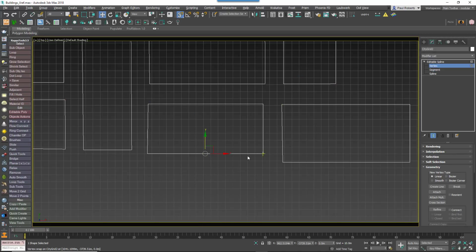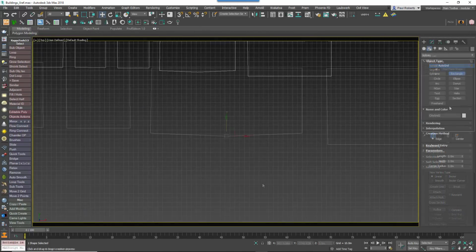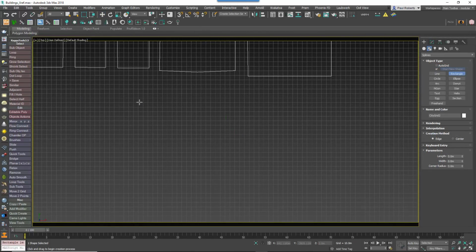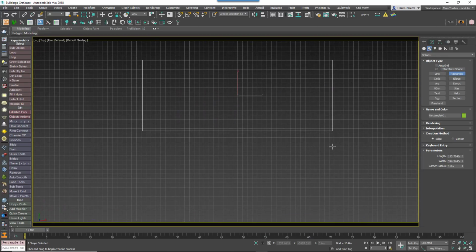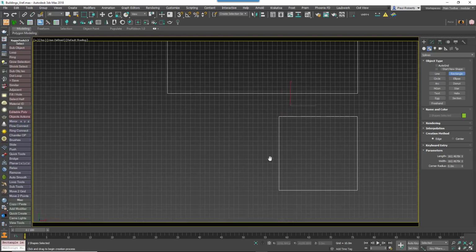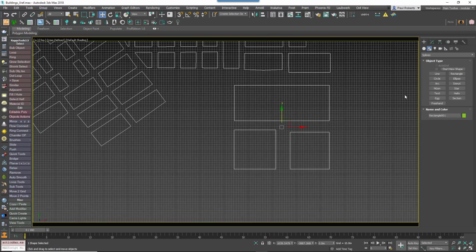Thirdly, for gradual changes in direction, use Bezier or smooth vertex types, but be aware that we won't be deforming geometry in this tutorial, so there's a limit on how curved splines can be before adjacent segments intersect. Once your city's created, it's a good idea to create a smaller collection of splines you can use to test out your procedural styles. This will speed up the creation process because Forest Pack and RailClone won't need to perform complex calculations on the entire city grid.